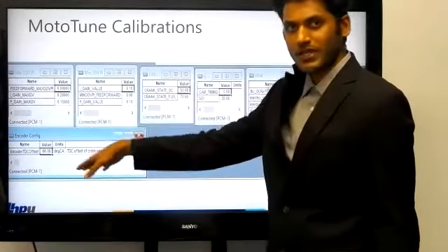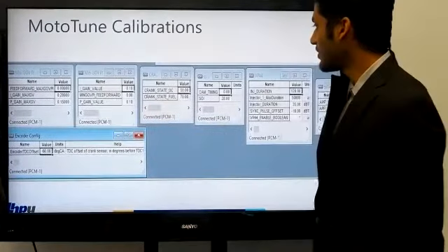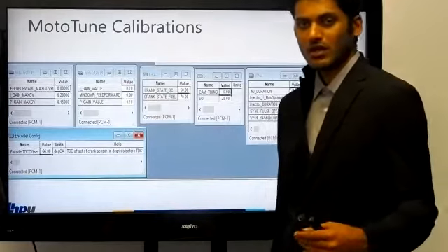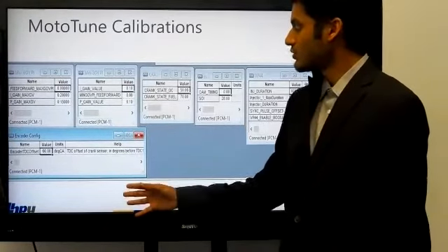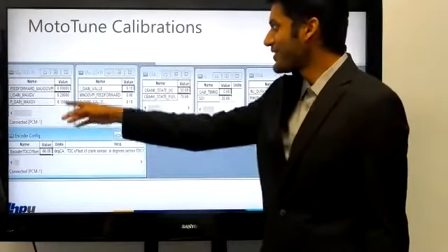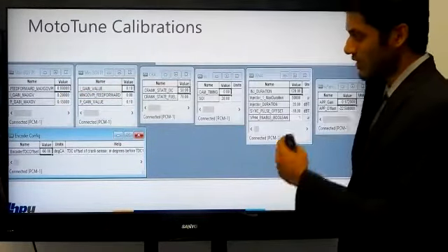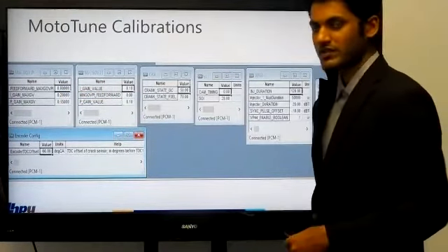In order to make the engine run at minimum governor and maximum governor, feed forward fuel is an effective way to do that because the engine needs a little push to make it run. So if we give a little bit of feed forward to both min and max gov, the engine would get the necessary fuel to run.